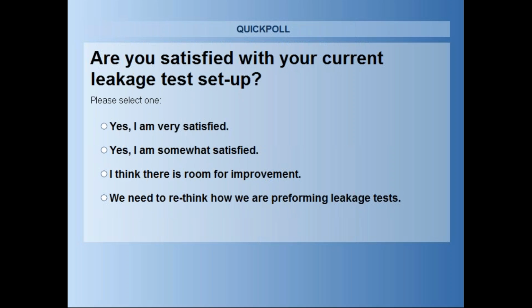I'm talking about earth leakage, enclosure leakage, patient auxiliary leakage, applied part leakage, and mains on applied part leakage. All of those can be done without moving your connections. You just need scanners, you need the test parameters appropriately set up, you need those scanner channels, probably most important, appropriately set up, and ideally you'd be using our software, AutoWare 3, which lets you save your test files to a PC. If an operator accidentally edits something, you can flash that back on.